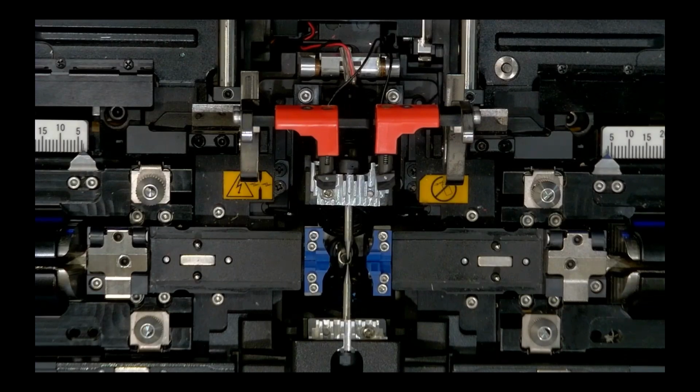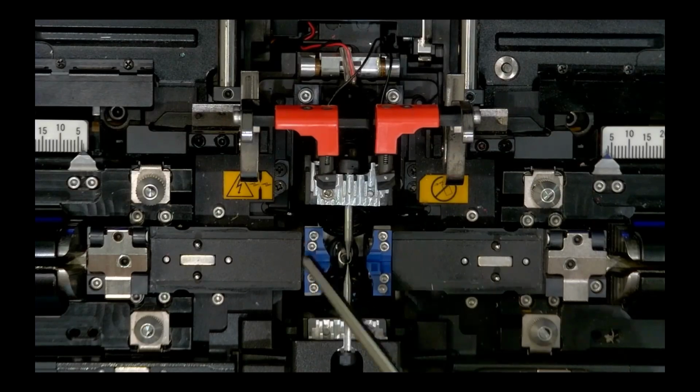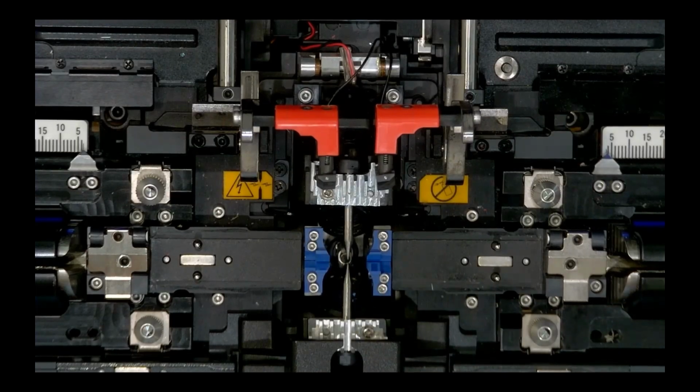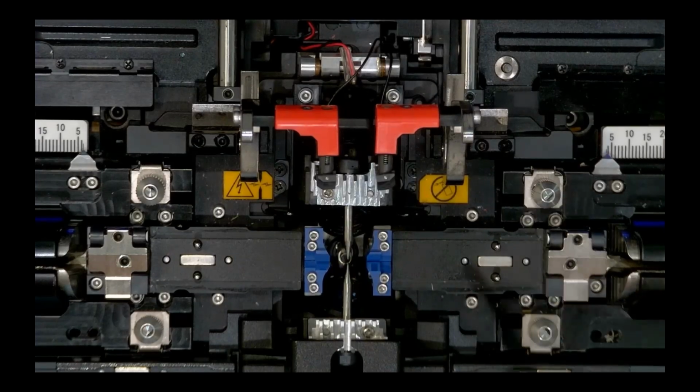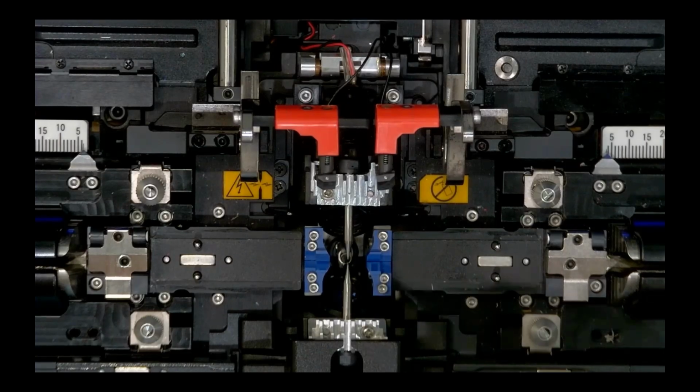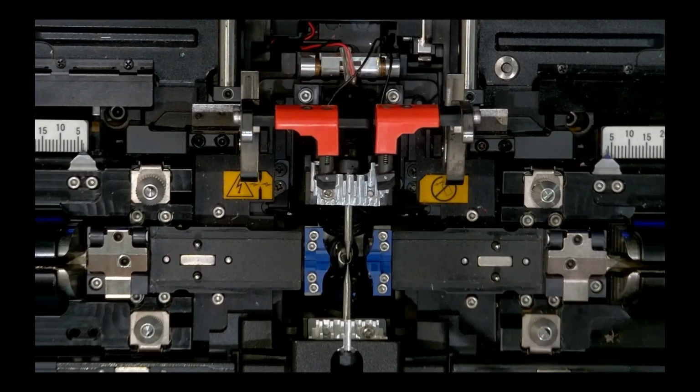And then moving outward from the electrodes, we can see that we've got our V grooves on either side. In the splicer menu, these are listed as your VA and VB V grooves because this is a split V groove block. What this allows is the splicer to physically resize the V grooves based on the fiber size that's loaded. So if you load a very small fiber size, the V grooves will close down to accommodate the smaller diameter. Or in the case of the P+, if you load a larger fiber size, those V grooves can open up to accept up to 1,250 microns in diameter.